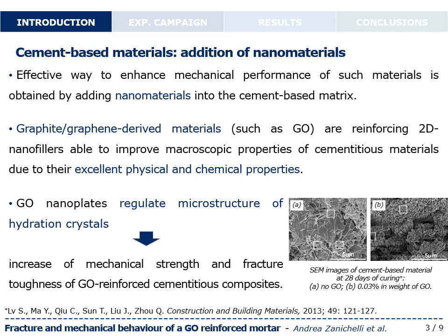Moreover, according to the technical literature, GO nanoplates can regulate the microstructure of hydration crystals during the cement hydration reaction, leading to an increase of the mechanical strength and fracture toughness of GO-reinforced cementitious composites. In such a context, the goal of the present paper is to investigate the flexural and compressive strength and the fracture toughness of a cement-based material reinforced with the 0.03% in weight of GO nanoplates.